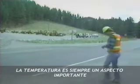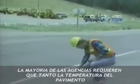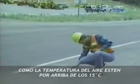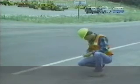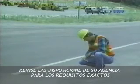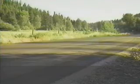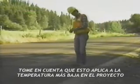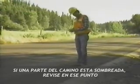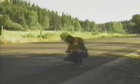The temperature is always an important consideration. Most agencies require both the air and pavement temperatures to be at least 15 degrees Celsius and rising. Check your agency's specs for the exact requirements. Keep in mind that this applies to the coolest temperature on the project. If part of the roadway is shaded, check the temperature in the shade.